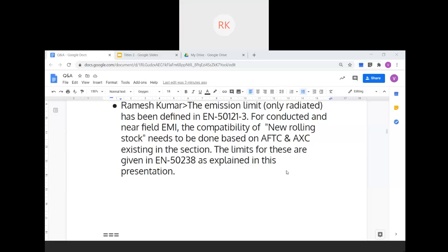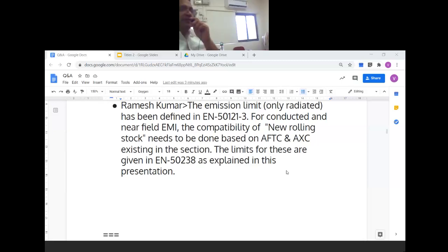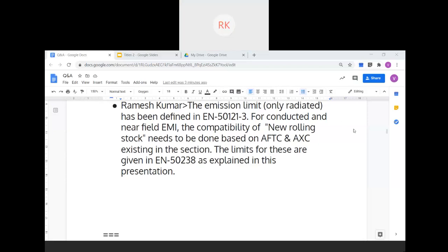Standardization is required here. I still pitch for some sort of a cage, an EMI cage, which can be put inside your OBC equipment, can be housed inside it. It can be kept anywhere in the locomotive, and the locomotive can create whatever interference it wants. We suppress it at the source. Right, just a suggestion. And the installation process for termination of cables, screen cables, asking for a powered axle and a non-powered axle for TACO purpose. These are points I think we'll have to sit down and have a sign off with the rolling stock equipment people. Yeah. So this is what I want to do.